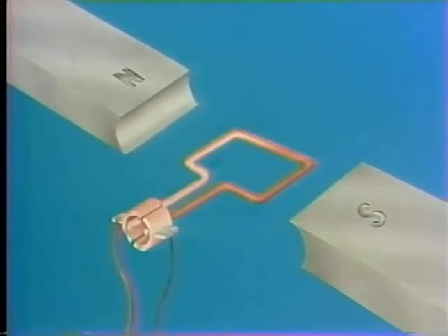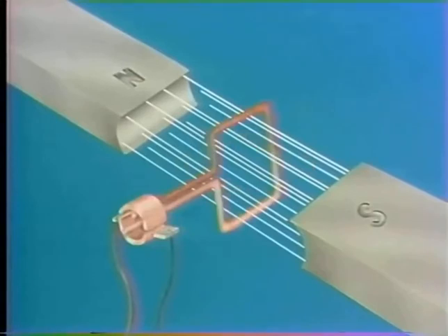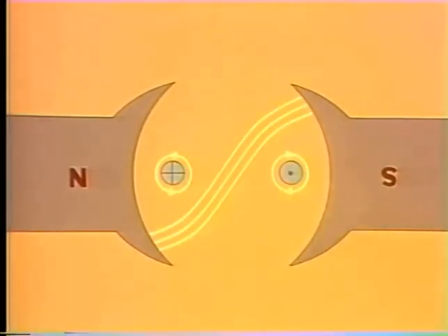You realize that as soon as current flows through this conductor, a magnetic field builds up around it. So now we have two magnetic fields. The main field located between the poles reacts to the field around the conductor. So the conductor rotates out of the main magnetic field. As you can see in this cross-section view, the conductor's magnetic field caused the lines of flux in the permanent magnetic field to shift. You can see that the direction of the shift is opposite from the direction in which the conductor's turning. And by the way, the rotating assembly of any DC motor is always called the armature.